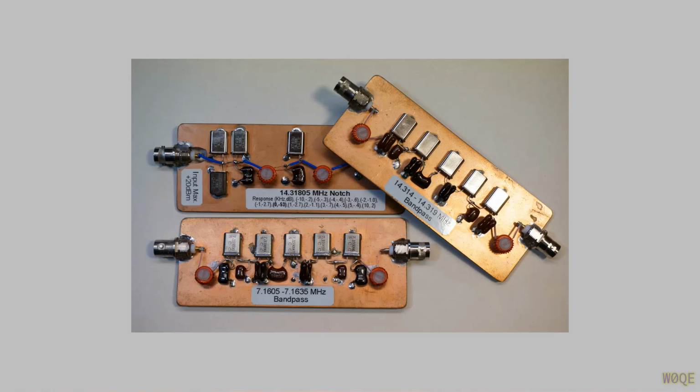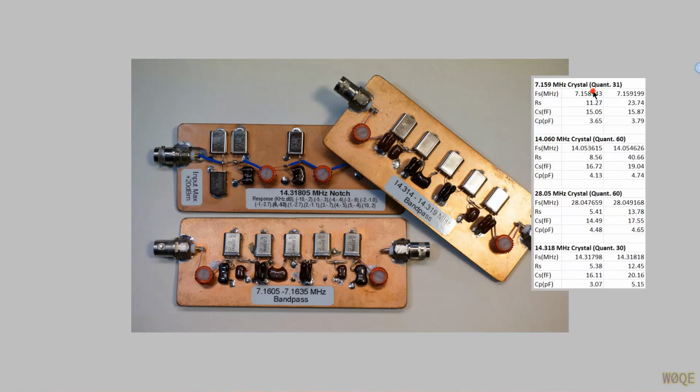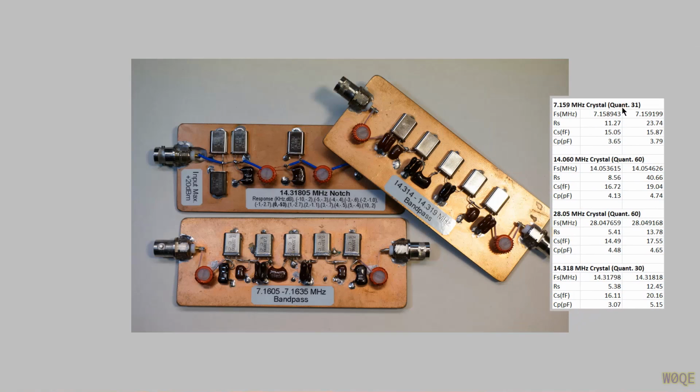And this video is about designing crystal filters and using SimSmith to analyze the design so that the resultant filter that we build is quite close in performance to what you designed. Crystal filters are a little bit tricky to design in that the crystal itself may not be matched to another crystal, even though they have the same frequency. And as an example, I made these measurements on some groups of crystals a while back.